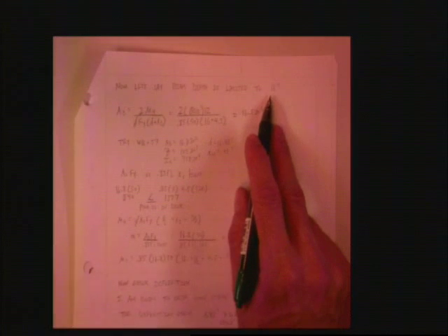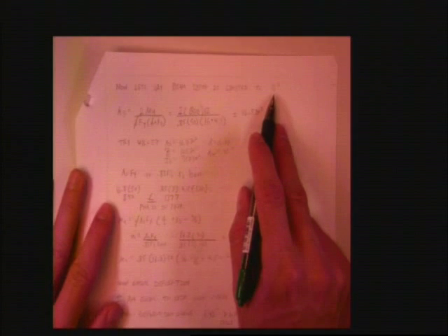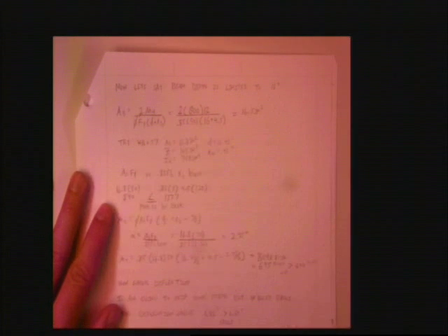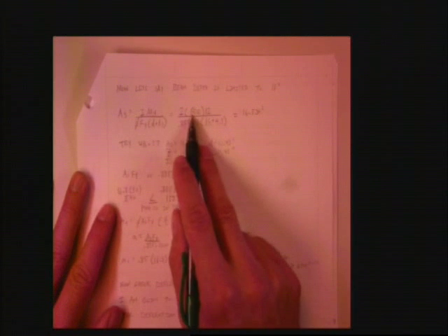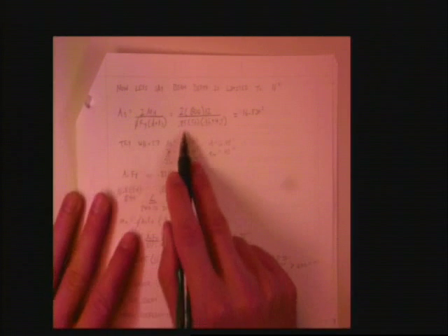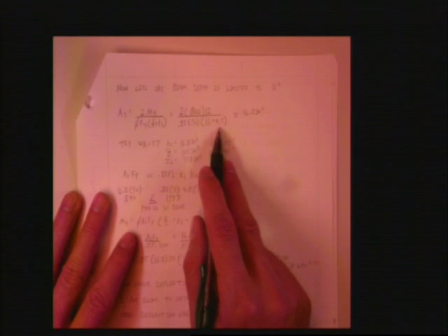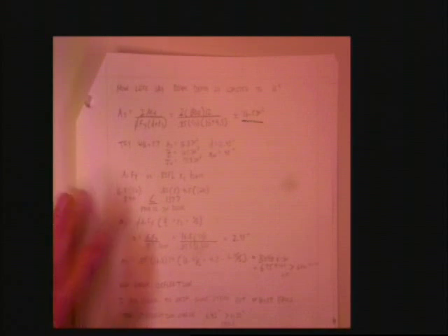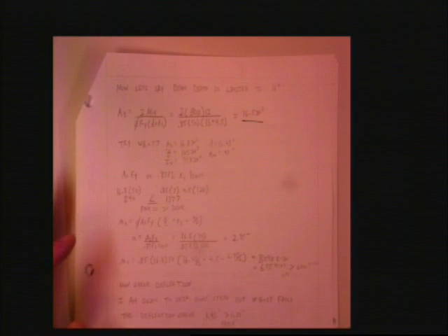That's cool. So, let's say we work the problem again. This time we're going to limit the depth to 16 inches. So the girder can be 16 inches below the deck. Again, that happens to you all the time. People will do that to you. So you say, okay, 2 times MU, change it over to kip inches. My phi factor is 0.85. Here's my Fy. There's my depth plus my 4.5. My area, 16.5 inches squared.